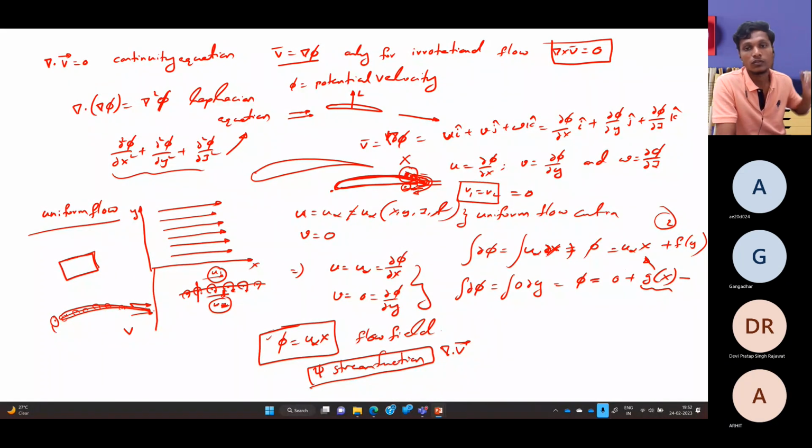So you keep in mind how the flow field responds with respect to the stagnation points. It is completely your way of placing the stagnation points on top or bottom. If you place them like this, how will the flow field react, and is it physically possible or not? Just because it is not physically acceptable or possible, the Kutta condition is stated like that. Okay, any more questions?